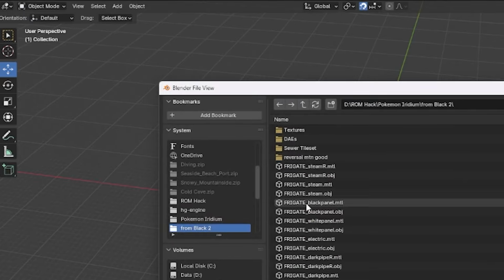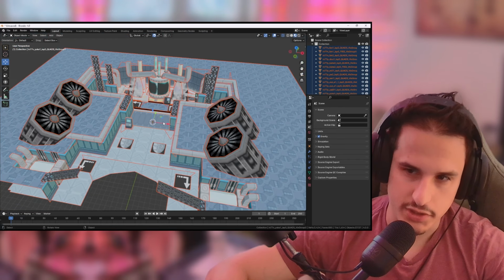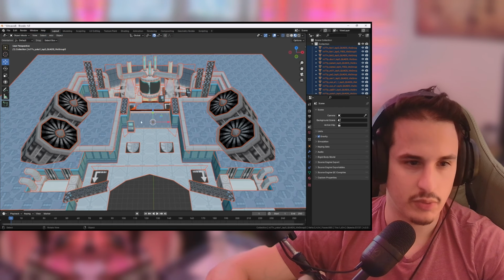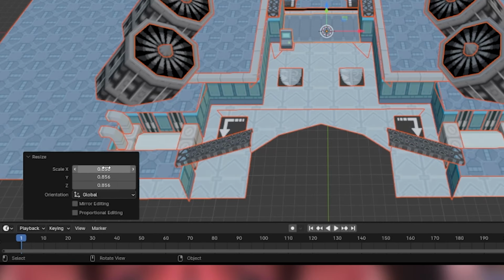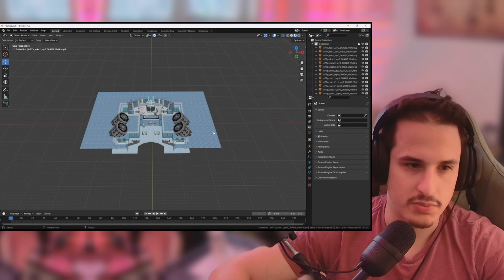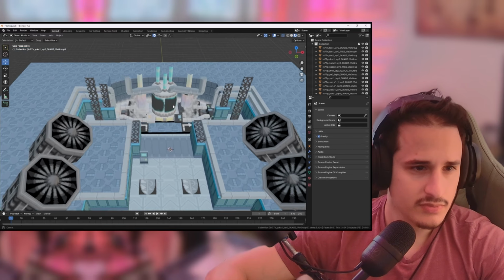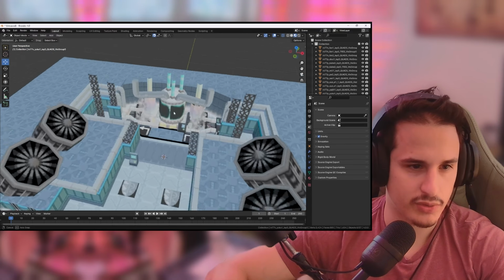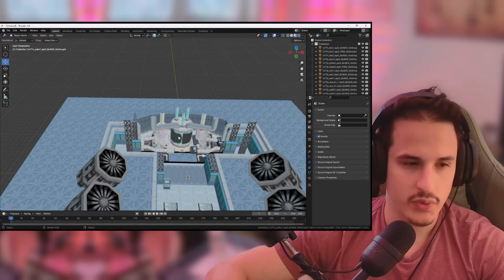I'm going to go Import Wavefront, and I'm just going to open this file. So wherever you have it saved, just open it up. And while everything's still selected, you're always going to hit S and just move it, left click, and then we're going to scale everything down to 0.0625, just because it exports too big, and we want it to be correctly sized to scale in the game, whatever we're going to be making. So you can use middle click to move around like this, and shift middle click to translate up and down. And we want this wall texture here.